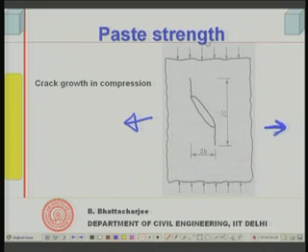So, that means there will be tension acting along the lateral direction, and this results in growth of the original crack, which was 2C here and 2B possibly the width here, growth of crack along this direction. So, failure of such a brittle material like cement paste and even concrete, particularly paste at the moment, under compression is also due to tension along the transverse direction. We can logically understand this. Such a material you try to compress from all sides, that is why I was showing biaxial.